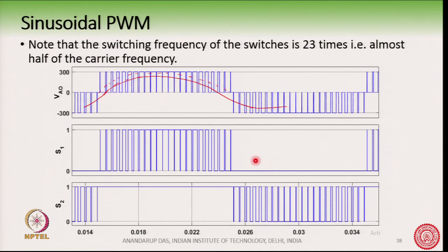In general, this is one of the challenges of NPC. For close to unity power factor and high modulation index, the outer switches of the NPC have much more losses than the inner switches. So, this is an uneven distribution of losses in the converter.